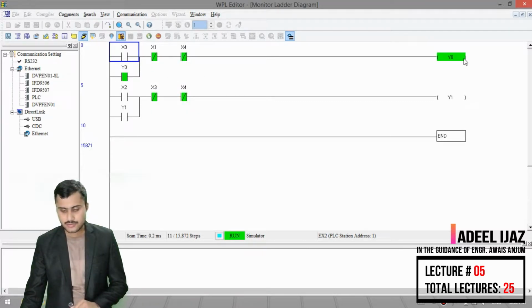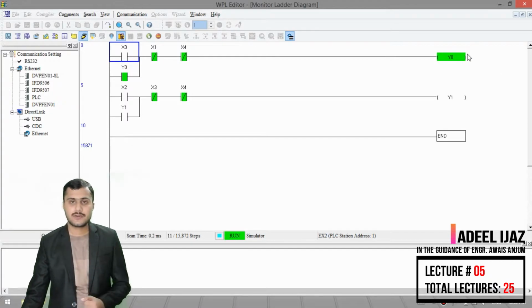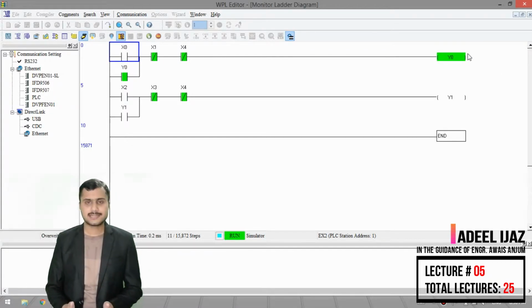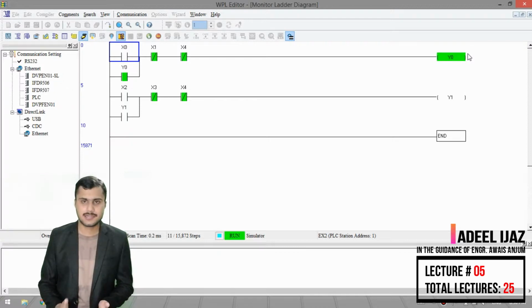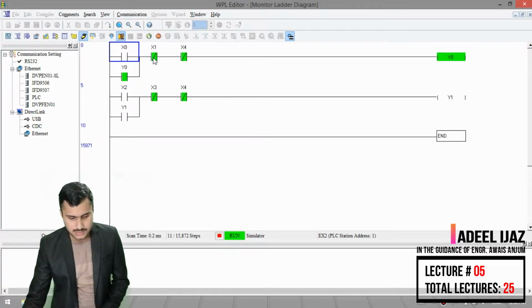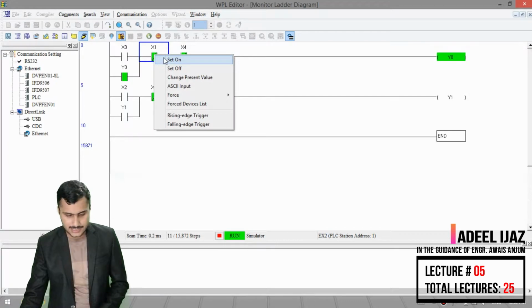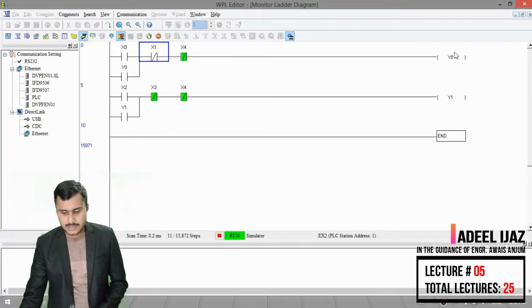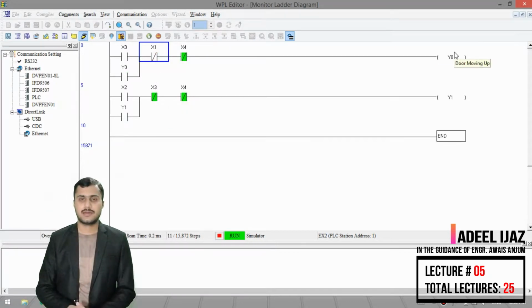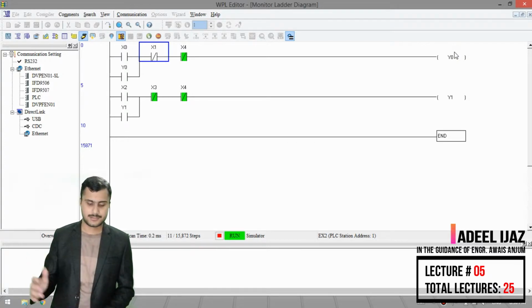You can see that the door is still moving in upward direction. Now let's say the door is fully open and the sensor attached on the top of the door is activated. The sensor on the top of the door is X1, so it will be activated, and now our door stops moving up because the door is fully opened.